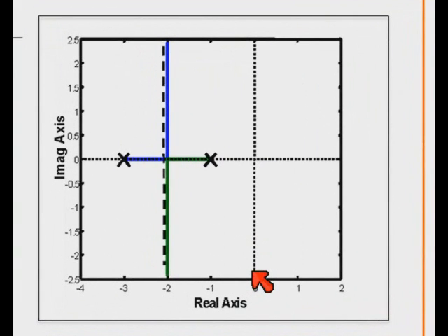It tells us that for all values of k, the system is stable, because the blue and the green represent closed loop pole locations which will always have negative real parts. There are no pieces of the root locus in the so-called right half plane to the right of the j omega axis. Anything over here, closed loop poles would have what?